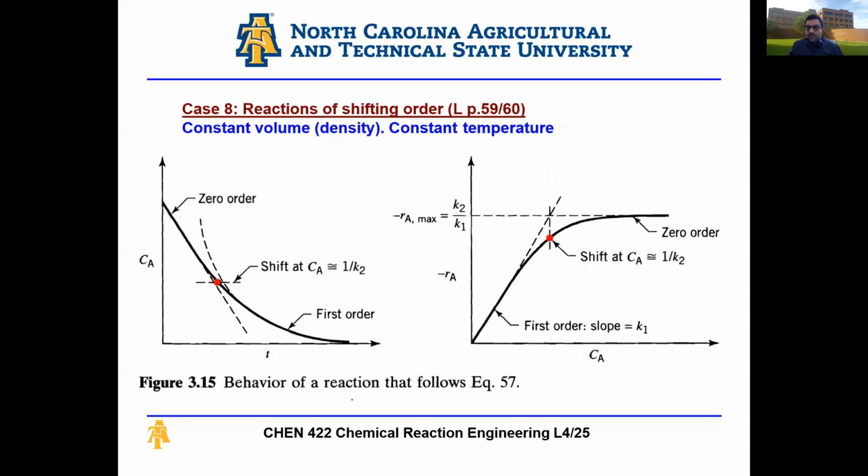And this is what they look like experimentally. So CA versus time, we'll find that you have a very clear linear slope and then it changes significantly. And as you can see, this is far away from C equals 0, because remember we said that if I have a zero order reaction, my points could look like this, but I see this conversion very close to the 0 point.